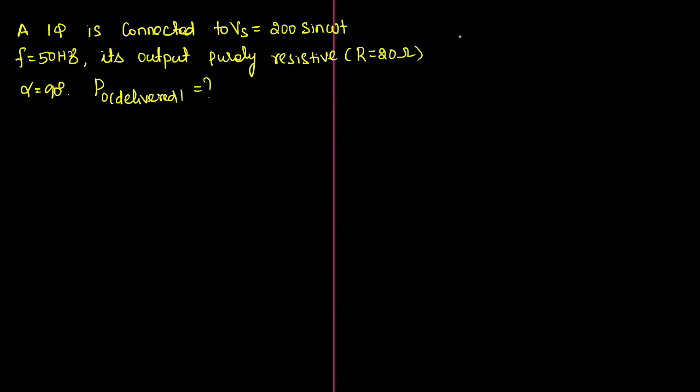Listen guys, listen. In the last question they asked power handling, yes or no? They have given the maximum peak inverse voltage, and then I have just taken V0 average, and the thyristor average current. These things you have to use only. They are asking what is the power that can be handled by the converters. If they are asking that, to know the converter power we have to go with the average.